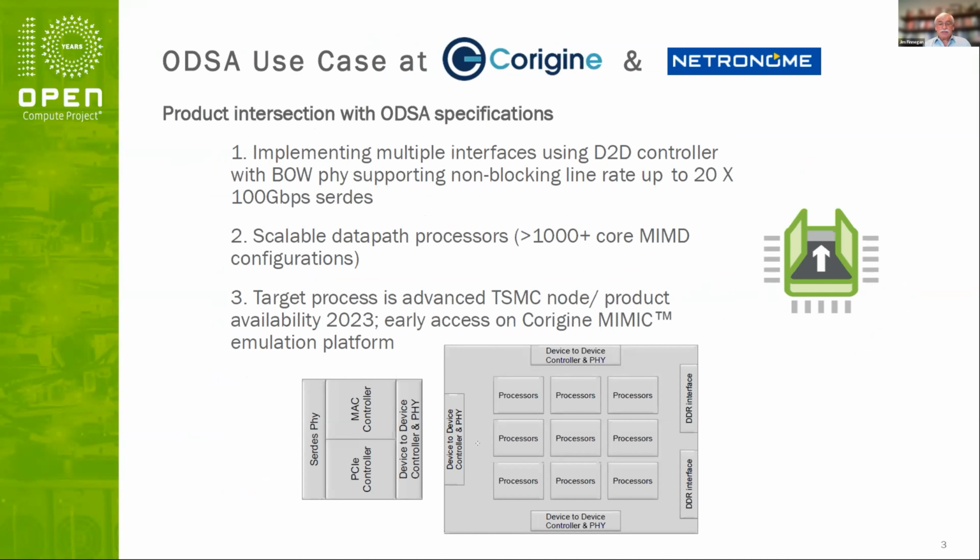I think jumping to the very specific practical implementation that we're doing. This is an example here, and what you can see is that the small chiplet is basically an I/O chiplet, except, for example, the number of SerDes, 112 gig SerDes, is more than 20. It supports PCIe Gen 6 plus a tuned MAC controller that can basically support very large packets without any blocking.